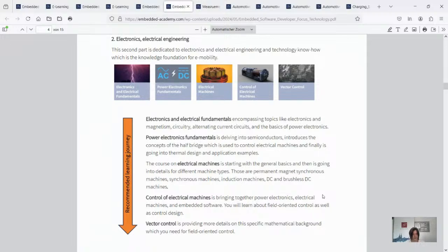For some areas, you also need power electronics. So not only having these 3.3 or 5 volts or up to 12 volts, but higher voltage, to change from AC to DC or DC to DC, DC to AC. So to have this conversion of energy. And power electronics, for example, you need within the charging station for your AC-DC converter, or in a solar panel device, or you need it for controlling electrical machines.